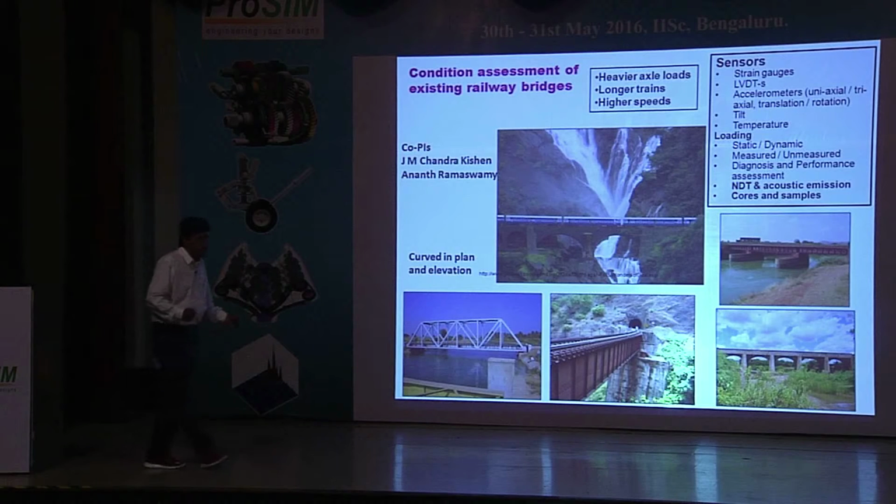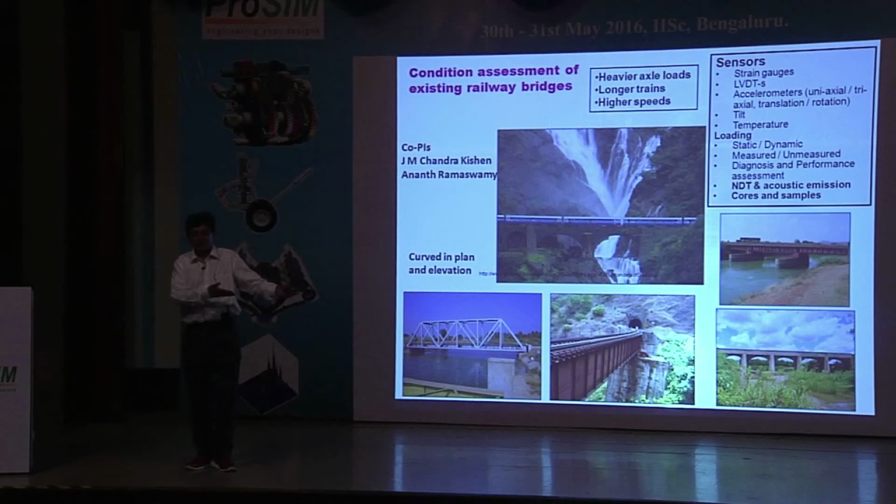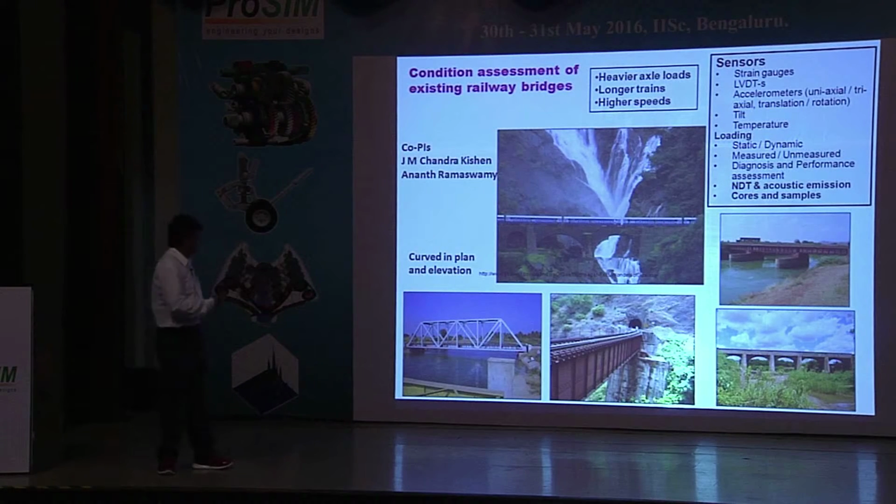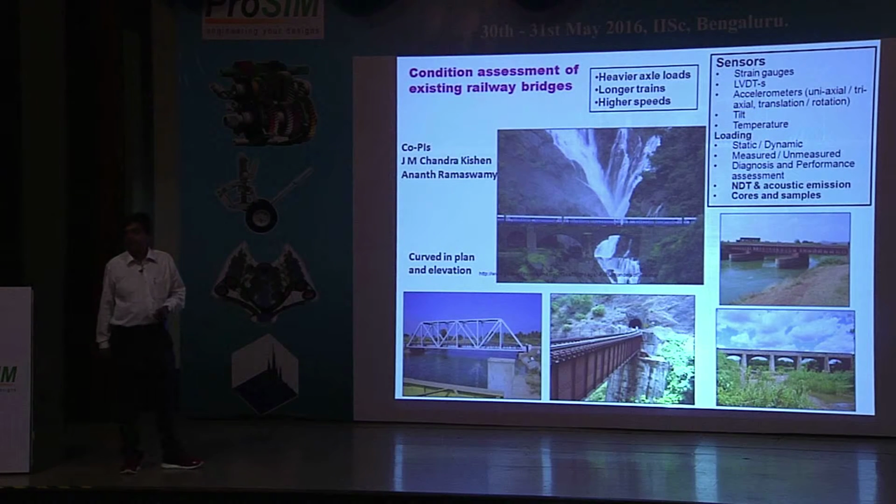Now, we were not permitted to apply the enhanced loads because they are all live bridges. So what we did was, we applied certain test loading patterns on the bridges, moving vehicles, accelerating, braking on the bridge, and so on and so forth, and we collected the dynamic response of the bridge, based on which we updated the finite element model for these bridges, and then on the updated finite element model, we applied the increased axle loads and other enhanced loading issues, and predicted how the structure might behave.